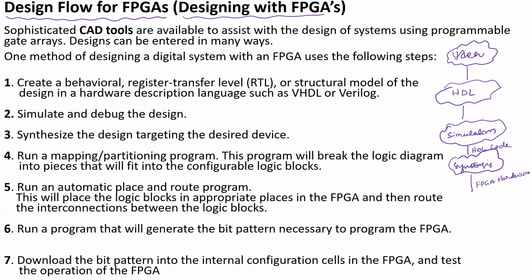Is it clear? Whatever the targeted FPGA you are considering, whether Spartan or Virtex or maybe Altera, according to that particular FPGA's resources, your program will be converted into those resources. So the text information will be converted into hardware based on the lookup tables, or I can call them simple CLBs. Instead of saying CLBs, better we consider the lookup tables.